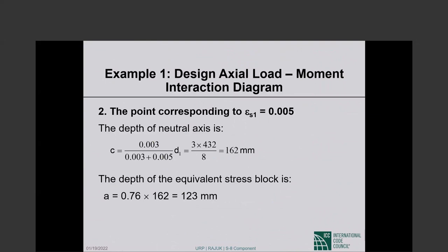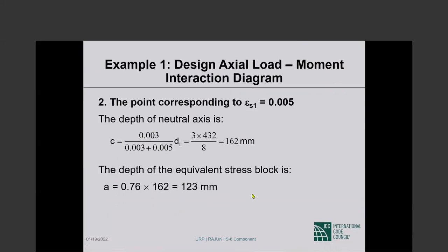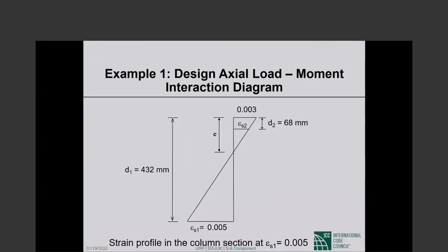This is the neutral axis depth from straight line strain distribution. The stress block depth is 76% of that, that's 123 millimeters.